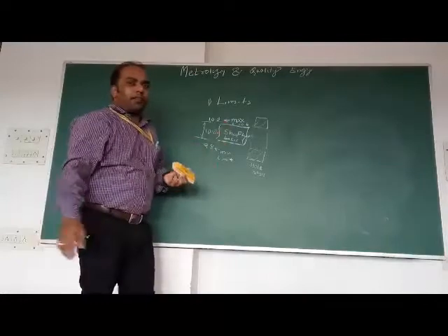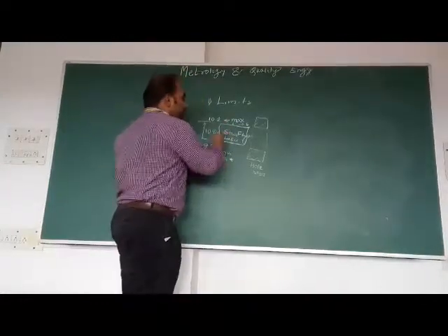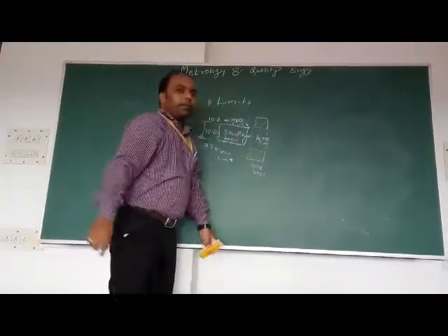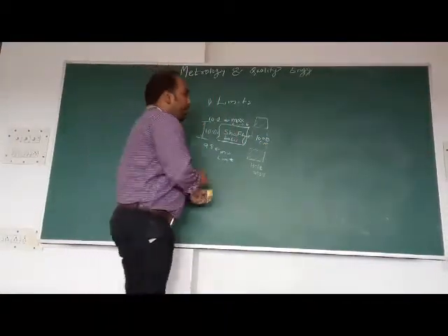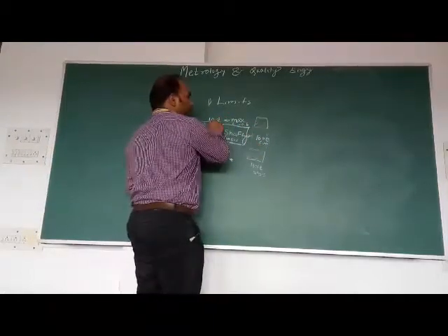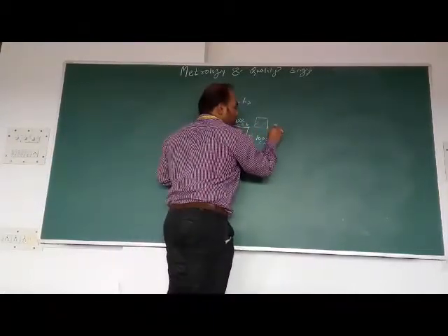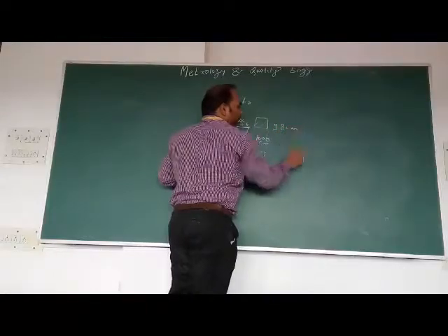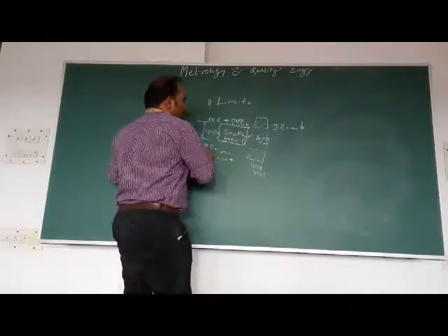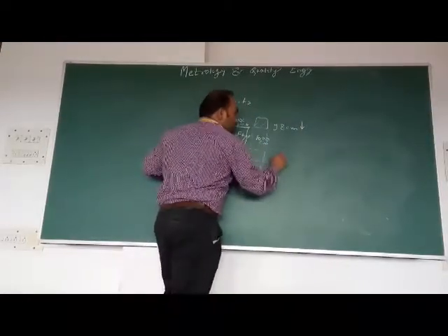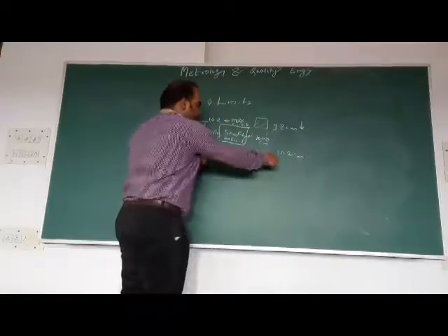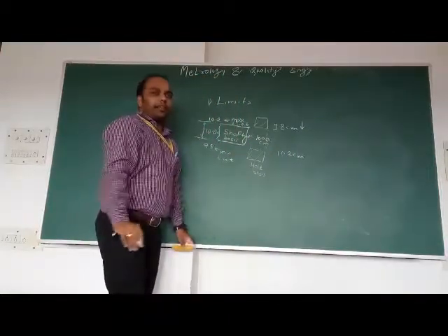Let us consider the same assembly where 10 cm is the required hole diameter. For the 10.2 shaft, the hole should be 9.8 cm, and for the 9.8 shaft, the hole should be 10.2 cm. Then and only then will the assembly be acceptable.